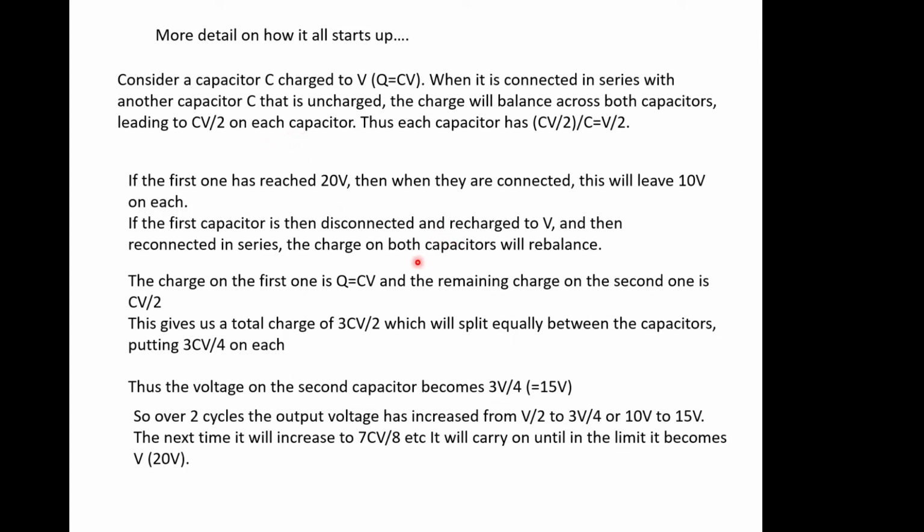And so eventually the final capacitance will be holding the final voltage, and this is showing it, stepping you through each of those cycles on that graph I just showed you, allowing you to get an idea of how quickly these things can charge up. And you can see in principle it never quite gets to the final voltage. It's one of these exponential things, but that's an explanation of how that happens.